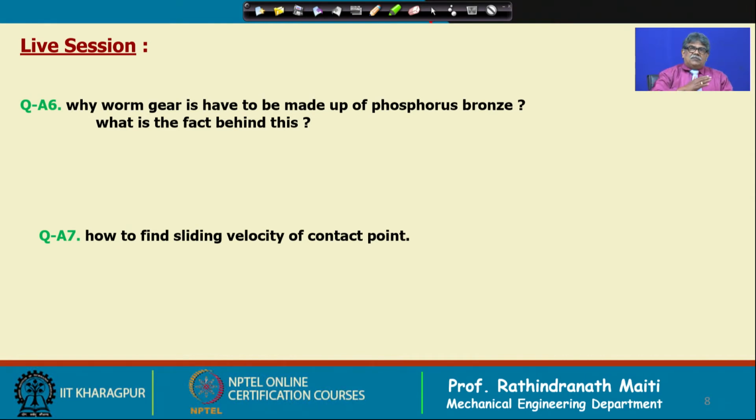Say for a particular angle of rotation, you know how much involute tooth has travelled on the involute path, then you have to integrate that path. You can take small angles, you can integrate to get the length and the time, because you know omega, and differentiate it, you will find the two velocities of this contact point on the gear teeth and pinion teeth, and then you can find out the relative sliding velocity.